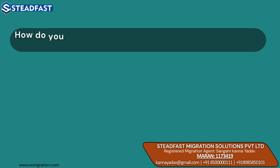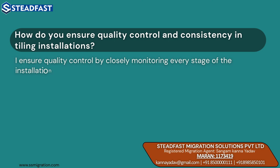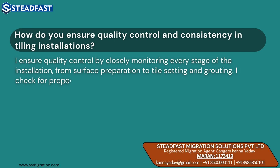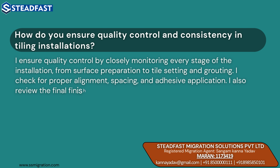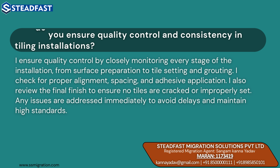How do you ensure quality control and consistency in tiling installations? I ensure quality control by closely monitoring every stage of the installation, from surface preparation to tile setting and grouting. I check for proper alignment, spacing, and adhesive application. I also review the final finish to ensure no tiles are cracked or improperly set. Any issues are addressed immediately to avoid delays and maintain high standards.